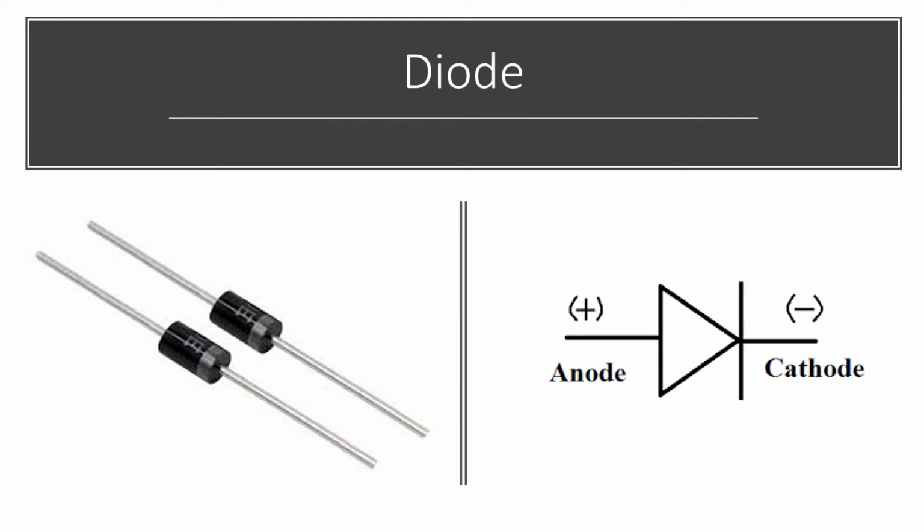All right, diodes. Diodes are something new. Diodes only allow current to flow in one direction. And they're shown using this symbol here on the right, where the arrow is essentially the direction of flow that is allowed. Wire your diode backwards in your circuit, and you're going to get no current, and your project is not going to work.